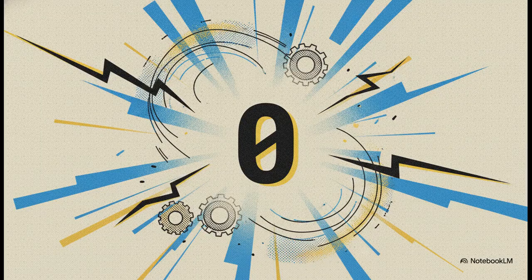But here is the truly mind-blowing fact about electric motors. Because torque in an EV is proportional to the current, and you can flood the system with electrical current instantly, an electric motor has 100% of its available peak torque, ready at exactly 0 RPM. Standing on the ground, without revving the engine, you have maximum rotational force right at your disposal. This is exactly why an EV pulls you back into your seat the absolute millisecond you touch the pedal. No waiting, just instant power.